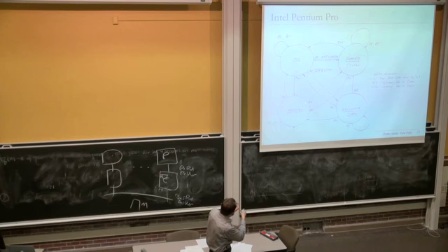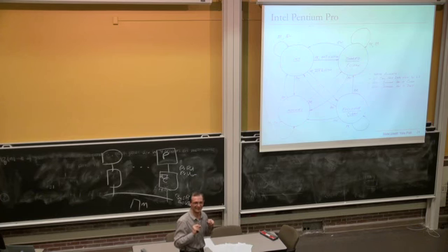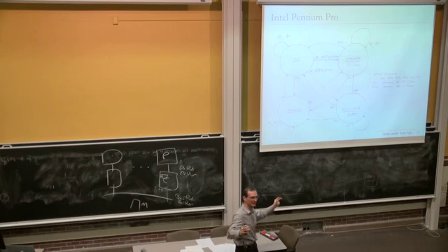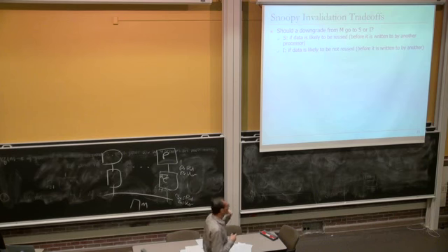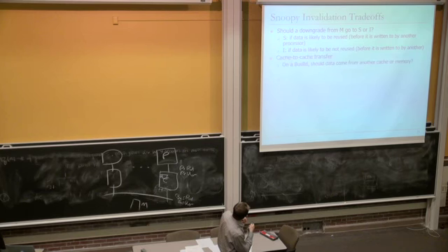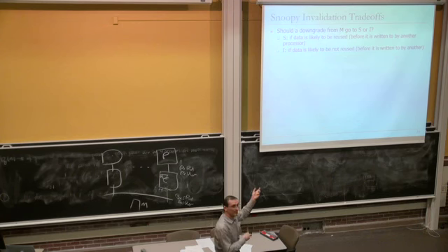bus read, if you go to the invalid state, the other processor can go to the exclusive state potentially, right? Exclusive clean state, if you write back to memory at the same time. So you may eliminate an invalidate later on. So there's another potential advantage. That's if you think about the protocols in the future. And that makes the design of cache coherence protocols interesting, I think. But if you do something like this, it becomes more complex also, right?